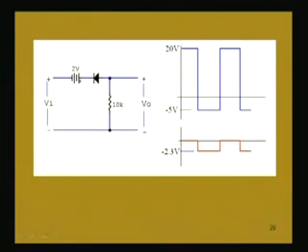So, we get 0 voltage in the positive half cycle, it will not be conducting, and the resistance R of 10K will not have any current through it. So, this voltage is 0 in the positive half cycle, but in the negative half cycle the voltage will be clipped at minus 2.3 volts. So, this kind of output voltage waveform we will be getting for this circuit.